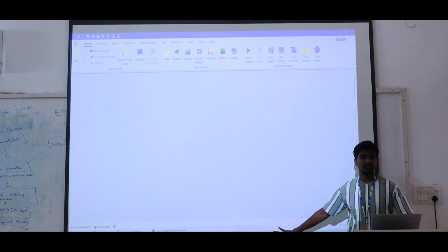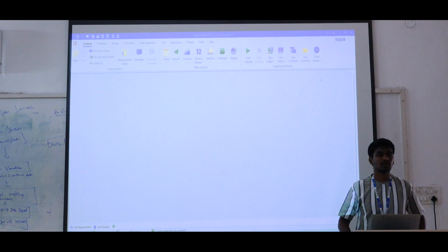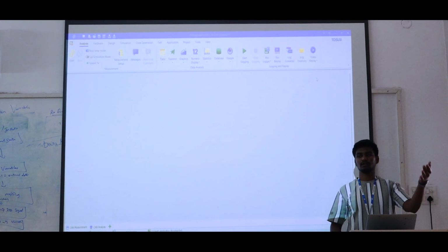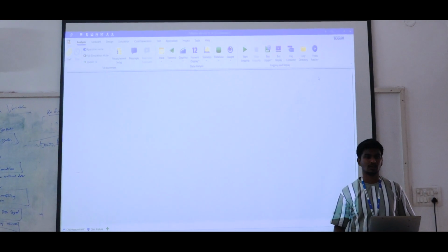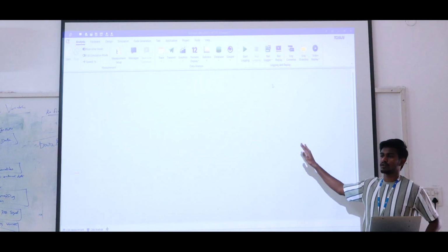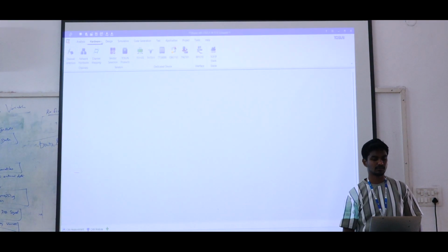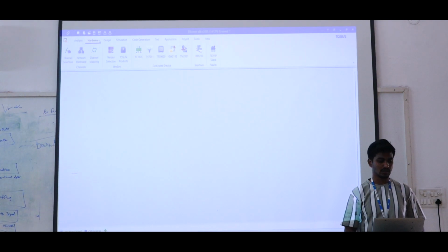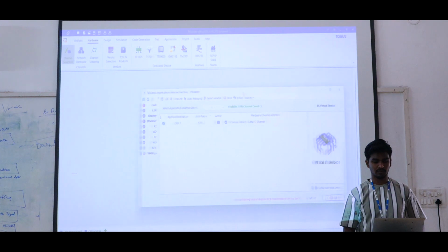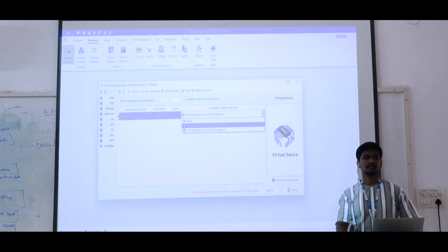I don't have any peak USB, but you all have the USB systems. Yesterday we did some programming on that kit also. One transmitter, one receiver. Based on the transmitter values, it will respond with 1 or 0 like that. Now the same value we are receiving in the trace window. So the first step is the hardware. Please connect the USB from any of your devices, then select the peak CAN channel.